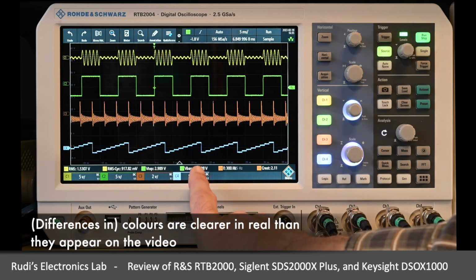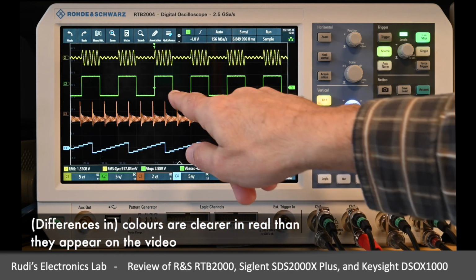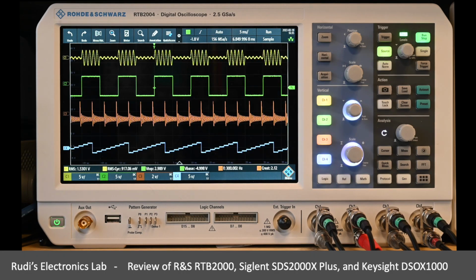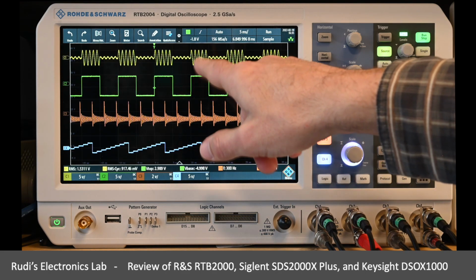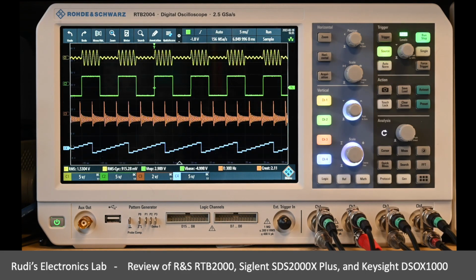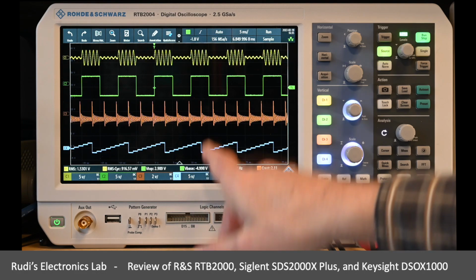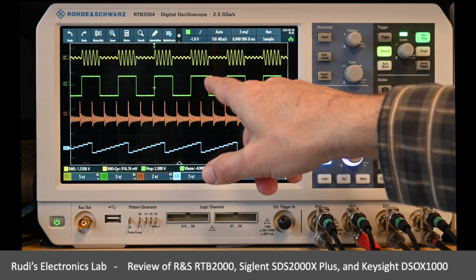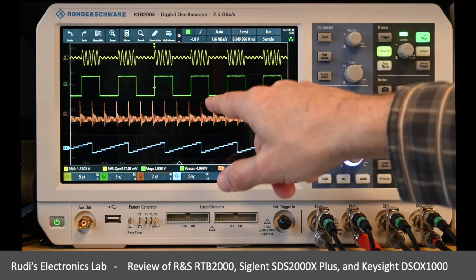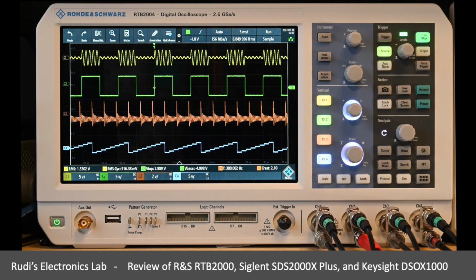We see voltage stop and voltage base. So this is basically the plateau value, not the peak values, positive and negative. There are separate ways to measure that, but these are the base, so it does not include any overshoot here. So I can see from voltage stop and voltage base basically how this signal is exactly that I'm using for the modulation of that AM waveform.